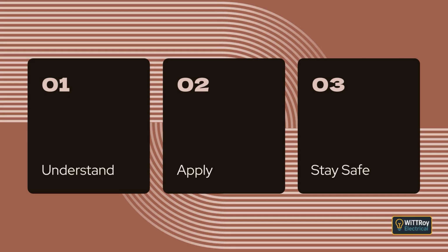Clause 3.3.2.5 Presence of corrosive or polluting substances. When corrosive or polluting substances are present, any wiring exposed to these materials must be protected or made from materials that resist corrosion. Different metals that may react with each other must not be placed in contact. Materials that can damage each other, or that may break down when placed together, must be separated. Some chemicals, such as esters, ketones, ethers, and chlorinated hydrocarbons, can affect insulation materials, so we must consider this when choosing conduits, enclosures, or cable types.